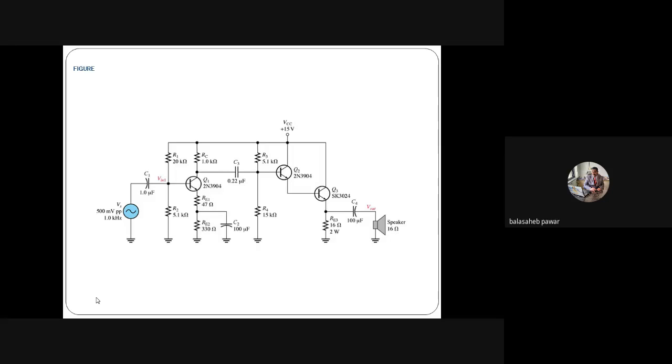We are interested in where the transistor is biased. That means we have to note down exactly how much VCE is. So for the shown circuit, if on that voltmeter we get VCE equal to 7.5, then what do we have to say? The transistor is biased exactly at the center, right? And the shown amplifier circuit is working as a class A power amplifier. Are you agree? Is it okay?